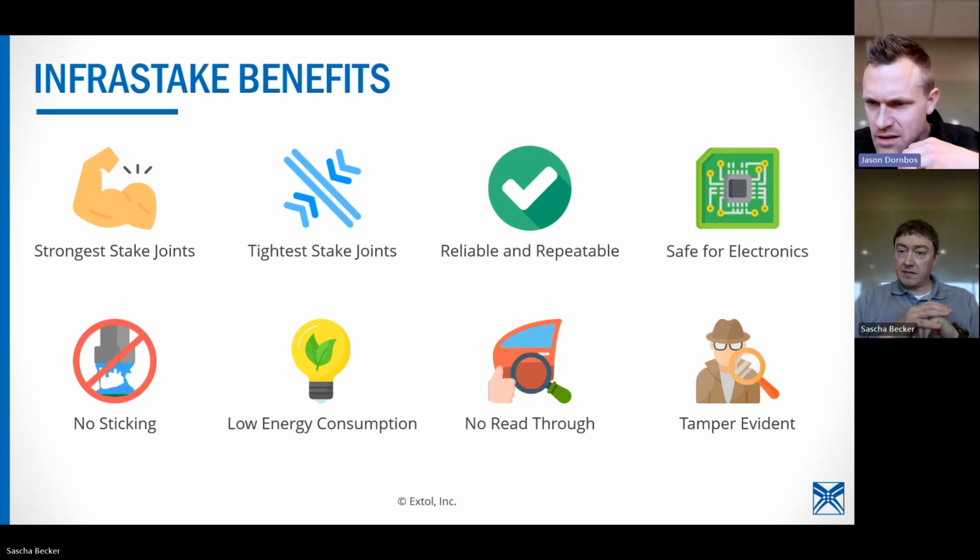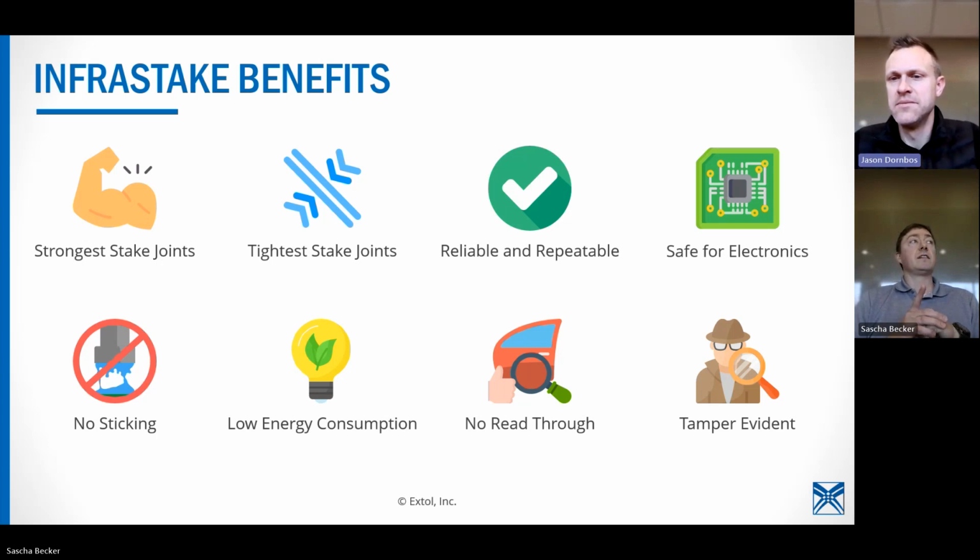So Scott asks if the non-boss material melts too. I would say no. But if we have a black mating component with, say, a white boss, the energy needed to heat that white boss is significant compared to what is needed to heat the black. So you might get a little bit of residual heating on the black, which would show up as maybe a small shiny surface.